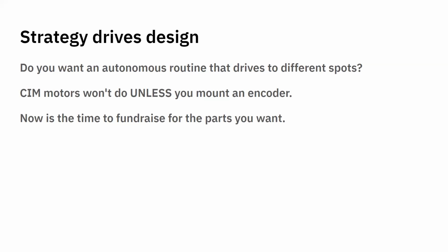And with that, you need to figure out how do you mount it, how do you wire it up, and all of that. So there are times where you look at the pricing and go, a CIM motor is really cheap and a Falcon motor is really expensive. But once you add up all the different elements of, I get this much power, I have a built-in motor controller, I have an encoder, dollar-wise, there's not a huge difference.